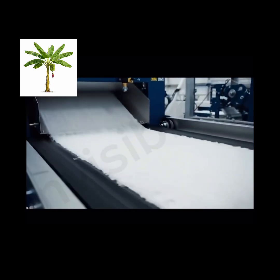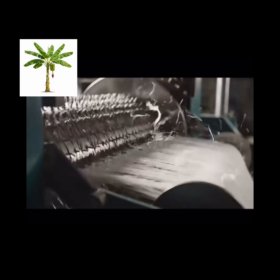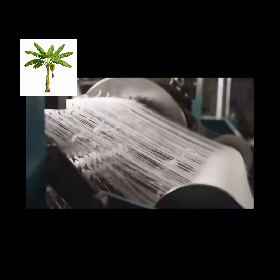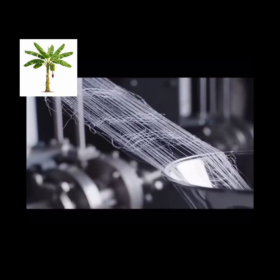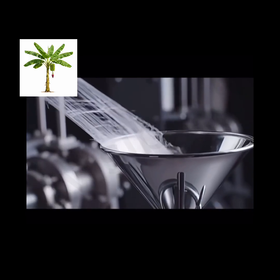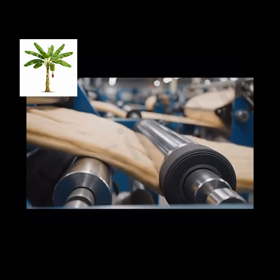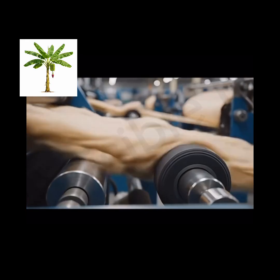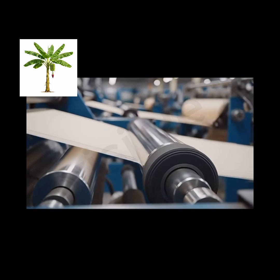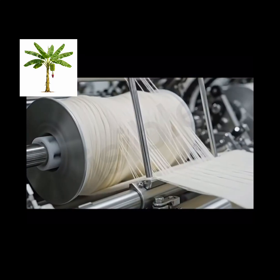Next is roving. Roving adds a small amount of twist to the fibers and winds them onto bobbins. This prepares the materials for final spinning. Spinning is where fiber becomes yarn. Spinning machines stretch the roving and insert controlled twist. The amount of twist determines the strength and texture of the final yarn. The yarn is wound onto cones or spools ready for use or for sale.